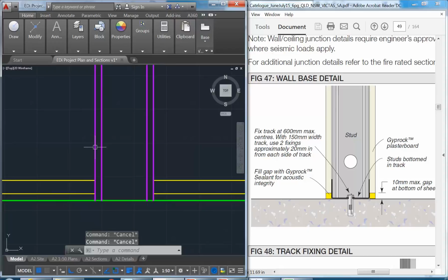Something behind the toilet should be bigger. Yeah, for toilet drains you'll often need a pipe that's bigger. So they're thinner than you might think, but bigger than that. They might need to be 120 or something. For a toilet, especially if you're going to do those ones that are fully integrated, where you've got the cistern and the drain in the wall, which you can do in a stud wall.